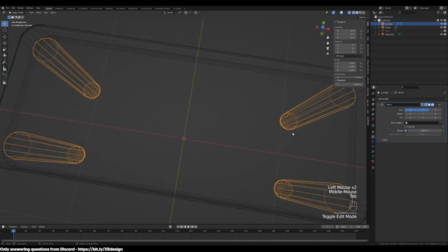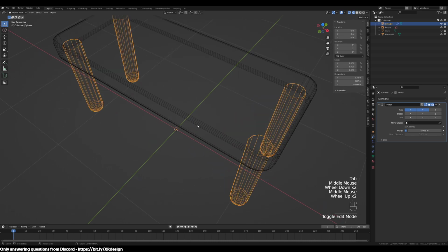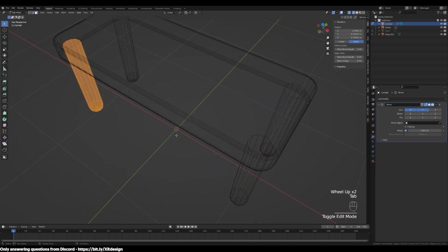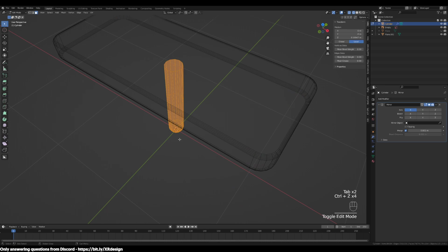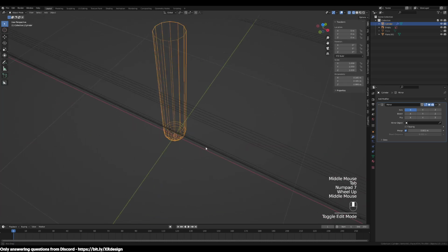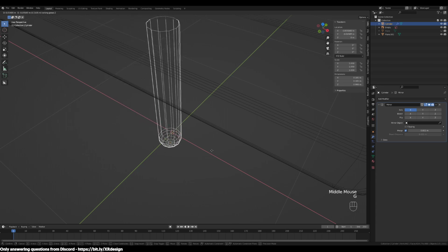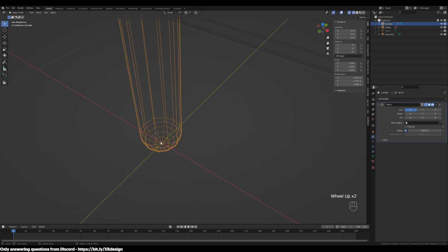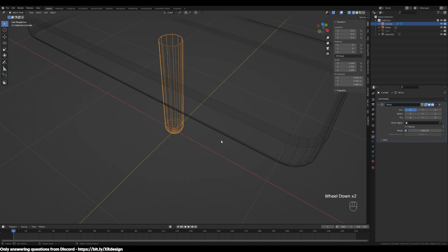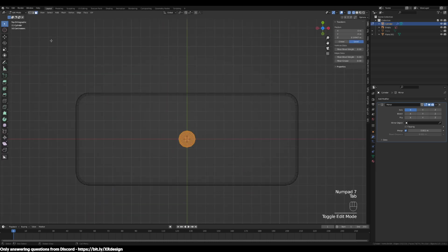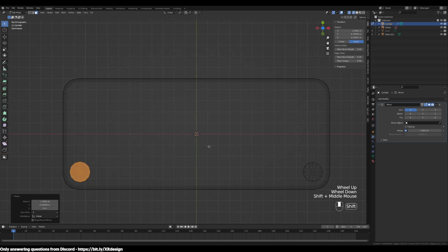And just to recap, if we did this in object mode, it won't work because, let me just undo. If we did it in object mode, you'll notice the object is moving with that object origin, so that orange dot. Whereas if we went into edit mode and moved the object, we're just moving that 3D model and keeping that origin in place. So always when you're tweaking something in mirror modifier, make sure you're in edit mode and you're tweaking the location of things.